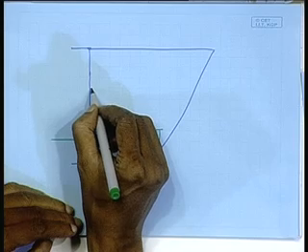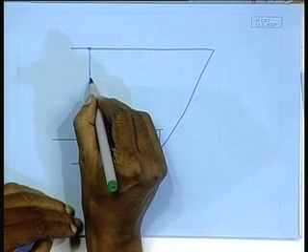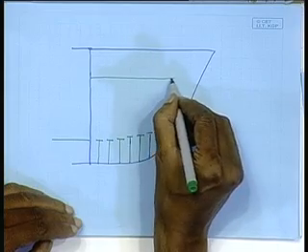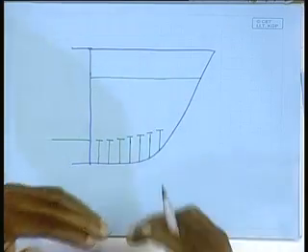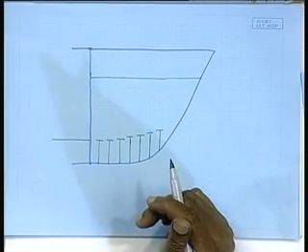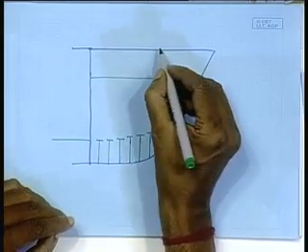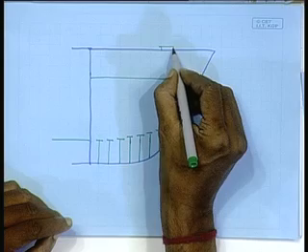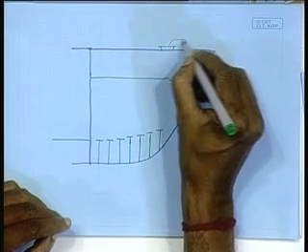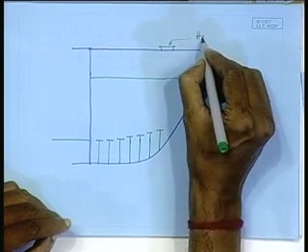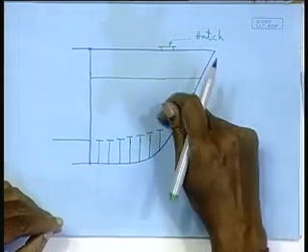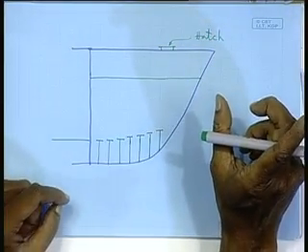Like here, in the forward there can be one lower deck altogether. In the forward end, one lower deck, right. The access to this deck will be through some hatch opening here. This is an access hatch, not a cargo hatch, because the forward peak is not meant for any cargo carriage. You cannot carry any cargo by rule, right.